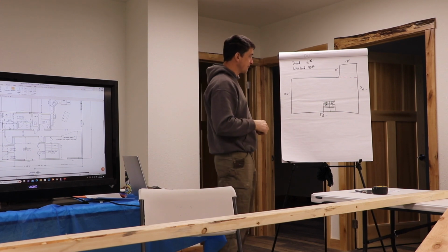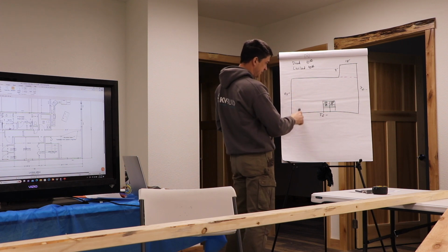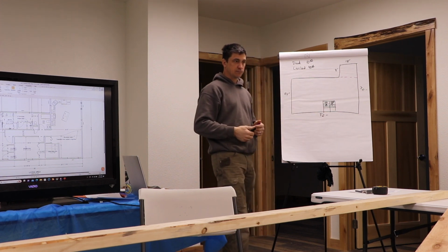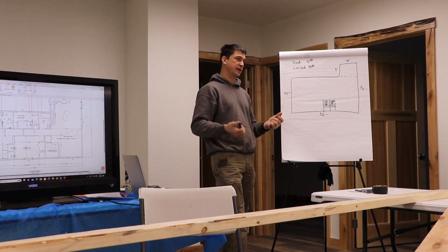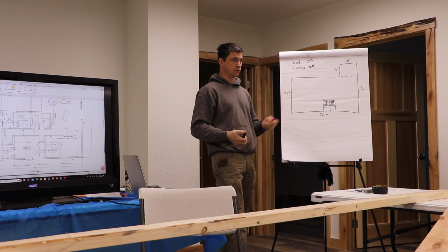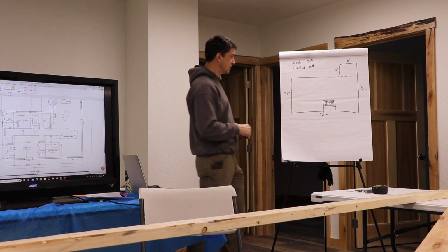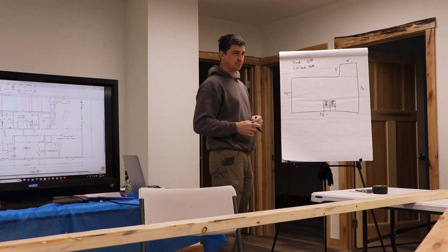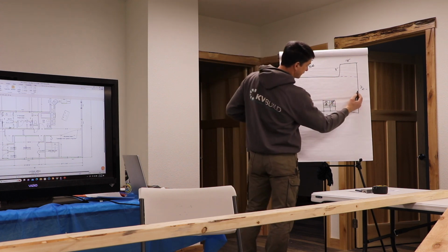So, do you think we want to try and clear span this so that the basement can be wide open? Probably not. Probably not worth it, right? Because it'll add a lot to the cost. We'll probably have to go to like a 24-inch floor truss or something like that. So what are we going to have to do then if we're not going to clear span that basement? We need to put support beams down the middle. Down the middle, perfect.